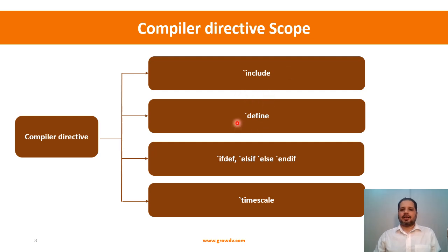So the scope for learning compiler directives is we will look into `include, then we'll look at `define, and then we will look at `ifdef, `elsif, `else, and `endif. There is one more flavor, `ifndef, that just negates. It's not a fundamental concept, it's derived based on this. And then we'll close it up with the `timescale.